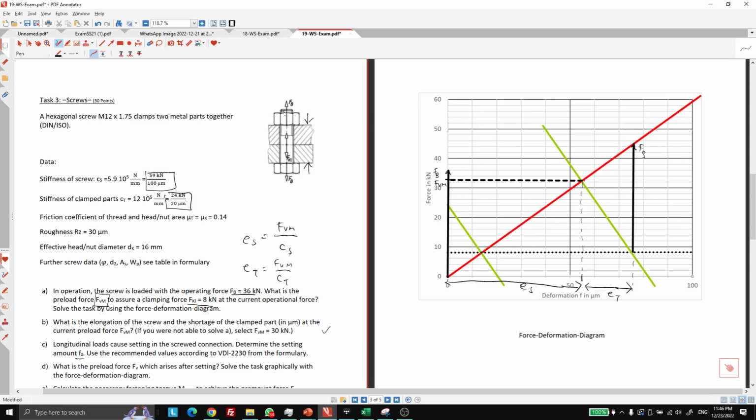So one thread area, one head, one nut, and whatever the head and nut is touching will not be counted as a separating plane. Not a separating plane, not a separating plane. This is a separating plane. So I have a 3 for thread area, 2 times 3 for the head and nut, and 1 times 2 for the separating plane, and I will have 11 micrometers.